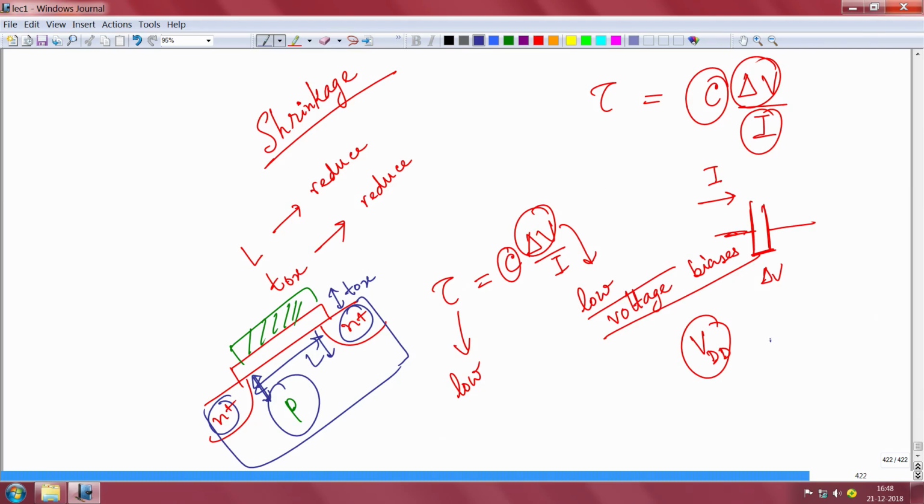The gate oxide, for example, has been reduced, and with the reduction, your gate leakage increases. So, that is why people have gone for high K dielectric, that I have already told you in one class. Using a high K dielectric, you can have a thicker dielectric, but the capacitance is the same, right. So, then short channel effects come in all these scaled devices, that also we have discussed in detail. Short channel effects come when a device has become very short, maybe 100 nanometer or a few hundred nanometer. Short channel effects can also kill your device, so you have to take that into account.